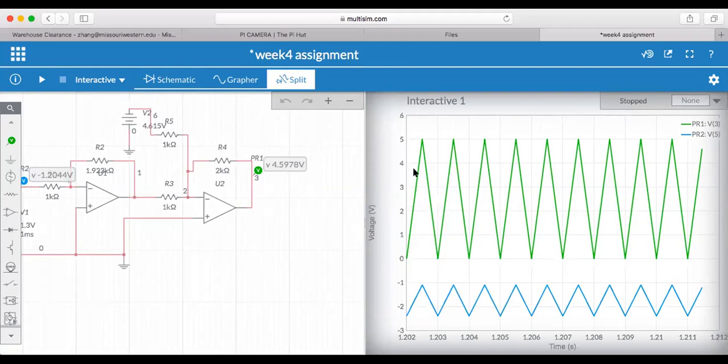The second change is it's shifted our input from negative 2.4 to 0. Also shift the negative 1.1, that's negative 1.1 right here, to positive 5. And now we have a standard voltage input to my controller.